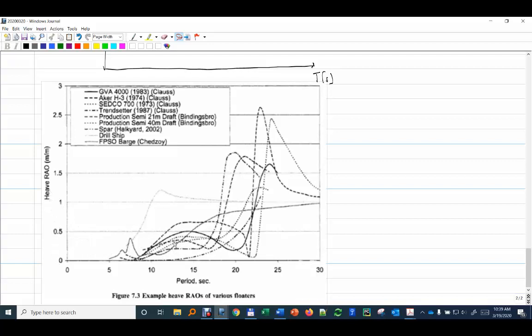You get like 0.25. But then if you start increasing the period, if you reach close to 20, it's going to change the response dramatically. You're going to get 1.75 or 1.8. And this is the peak that we were referring to before: each structure, for one particular movement, has a specific natural period. So you see these peaks here. For example, this peak is quite exacerbated.